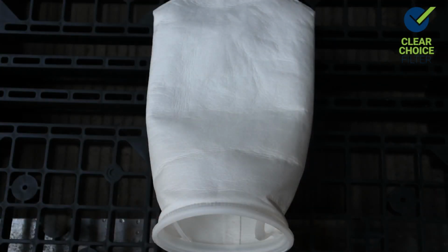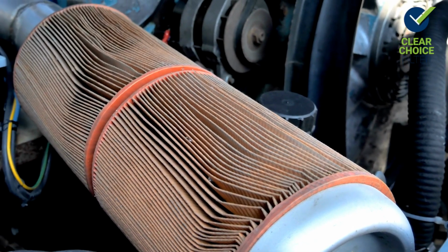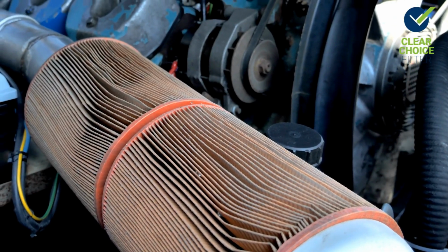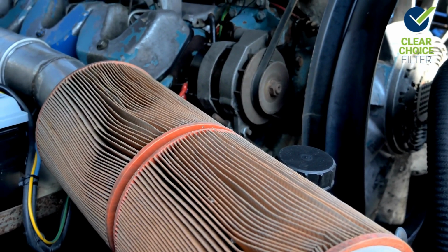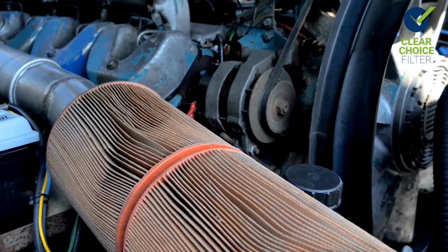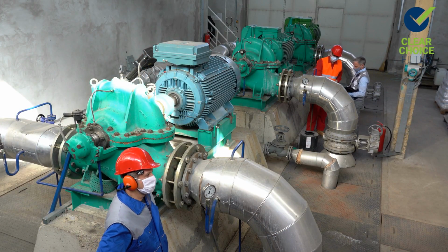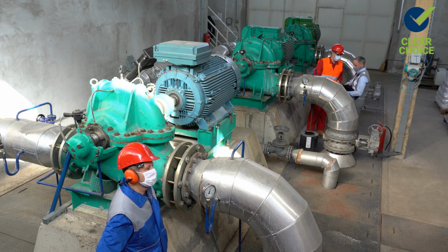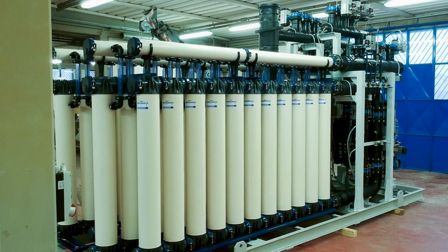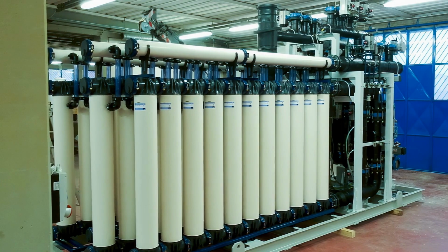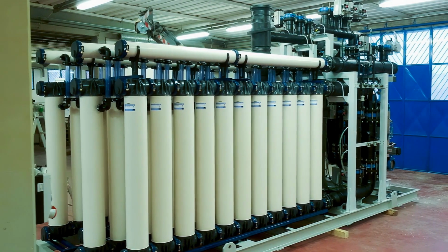Bag filters, which use a porous material, primarily rely on screening to remove debris, dirt, and larger contaminants from liquids and gases. Other types of filters that use screening are pleated filters that provide large surface area of filtration but limited depth of media. These filters are widely used in applications to protect dynamic equipment such as pumps and compressors, or even as a pre-filter to fine filters downstream because of their low cost.